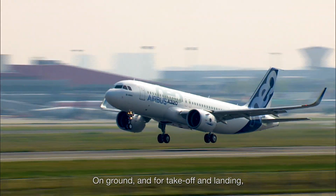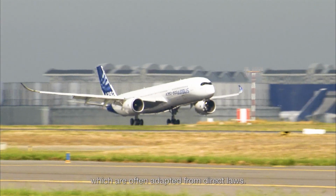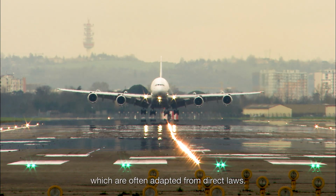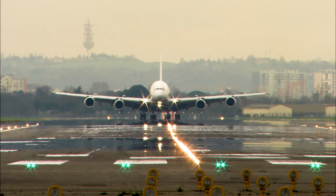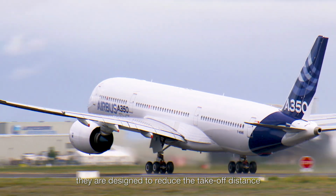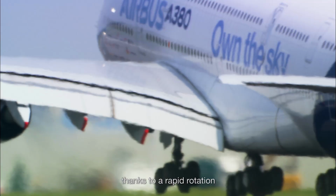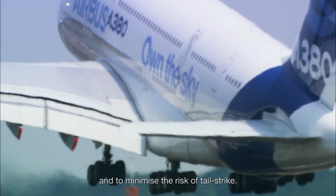On ground and for takeoff and landing, there are specific control laws, which are often adapted from direct laws. For takeoff, on the most recent models, they are designed to reduce the takeoff distance thanks to a rapid rotation and to minimize the risk of tail strike.